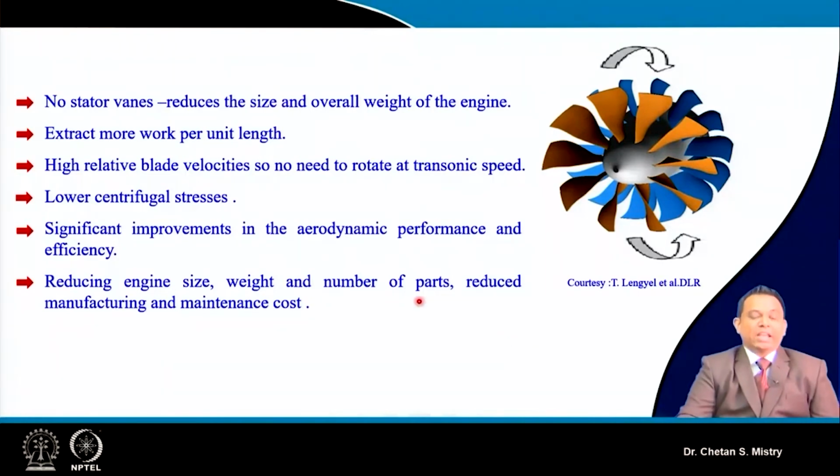Secondly, we can extract more work per unit length. Since we have fewer stages in the contra-rotating configuration, for the same length as your actual engine, this configuration gives a higher amount of work that can be extracted.